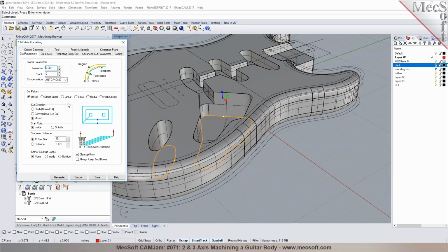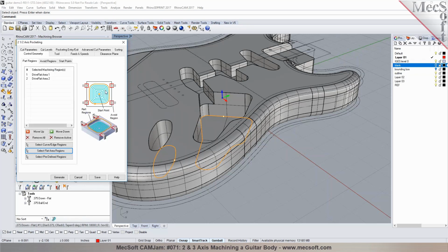But for our depths, the reason that they didn't have this included in it is because this pocket here only starts at this Z level and goes down, because this top part's already cut out. That's why they had it in a separate operation. You follow me? But it's going to be cut in 2 separate levels, is it? Well, this one, let me go ahead and finish it, and then I'll show you. Let me get rid of this one. Let's remove that one.